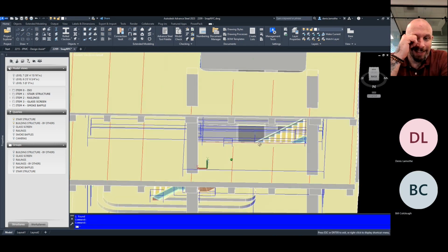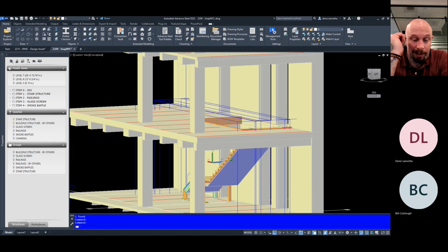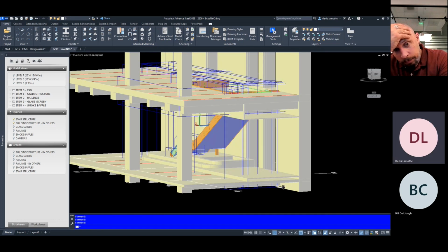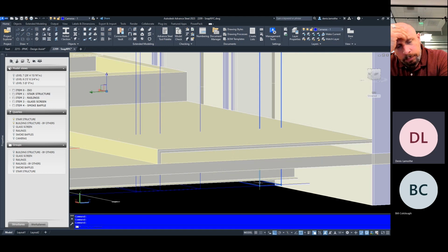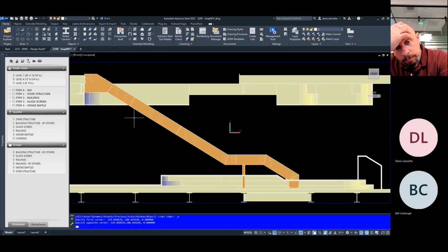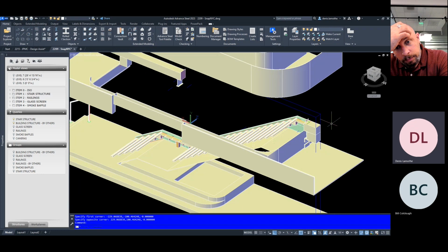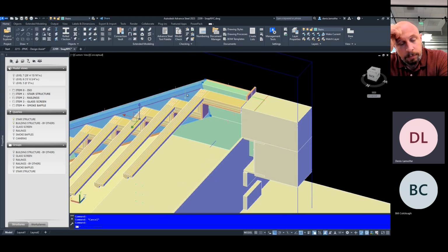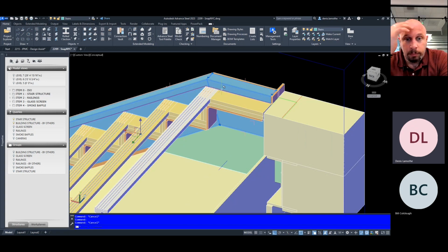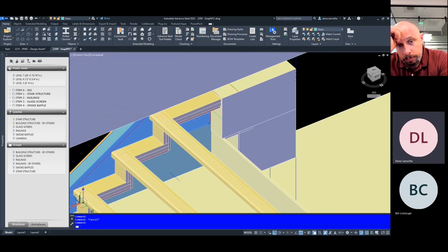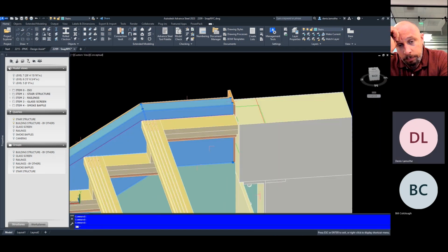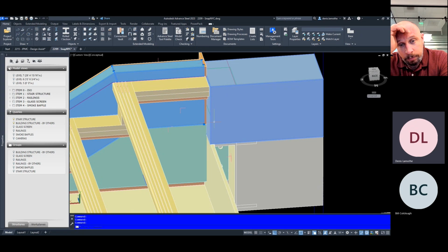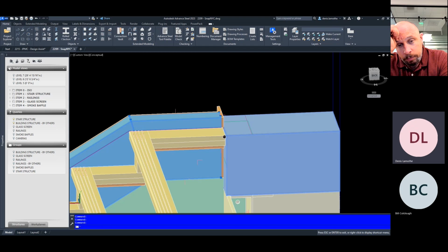The computer's a potato, so it's not really fast either. Let's try this one here. What I was trying to show is, oh, that's why. Okay. So we would have a stringer, whether it's HSS, channel, or any other. We'd have it return to the face of the opening. And in this case, the slab depth wasn't thick enough that we could provide an attachment plate.